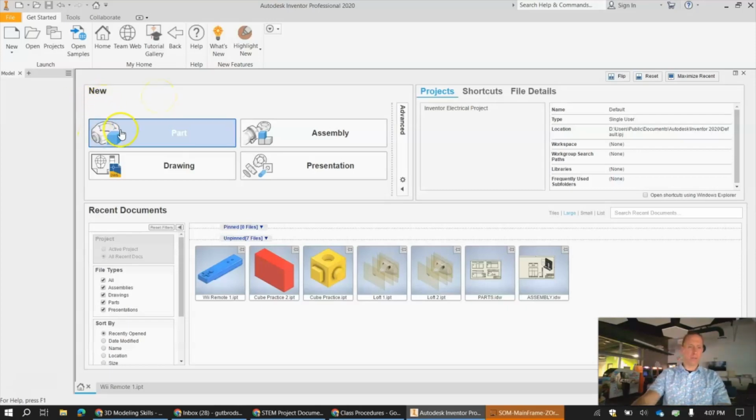And then, if you notice, it's showing a single part. Then we're going to assemble those parts in the 3D modeling program, and that's going to be your evidence that your dimensions are correct. That's going to be your proof. If you're making a box, your assembly has to fit together. You're not going to have any gaps in it, and that's going to be proof that your dimensions are correct.